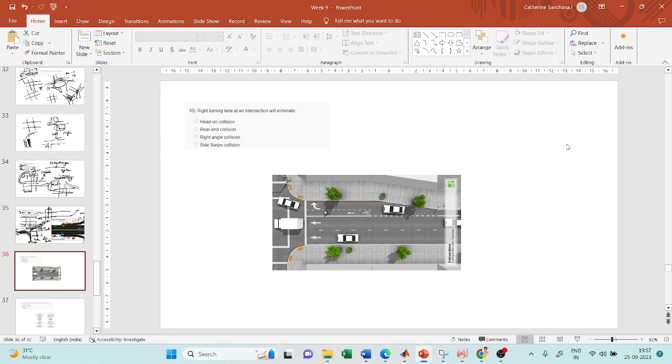Just a second. In the solution also it is taken as tan theta by 2. And theta stands for? Theta is the angle of the circular curve. It is the transition plus circular curve. The tangent length should be LT by 2 plus R plus S into tan delta by 2.